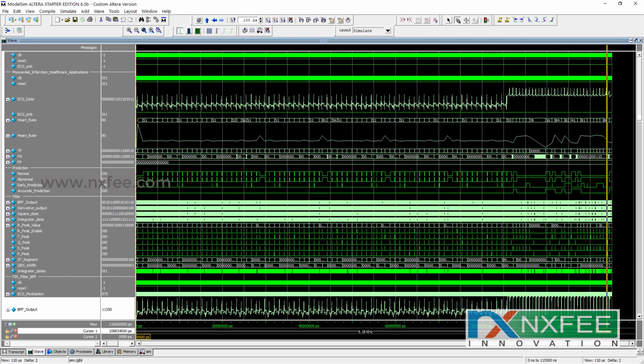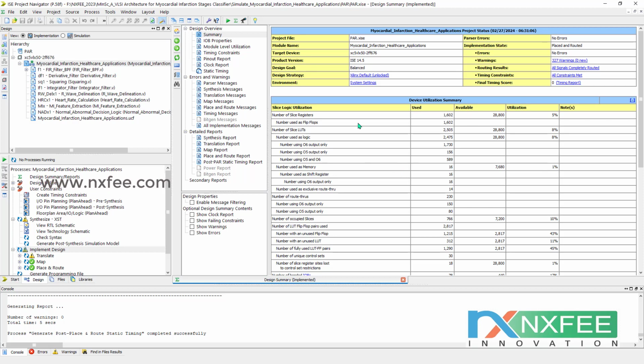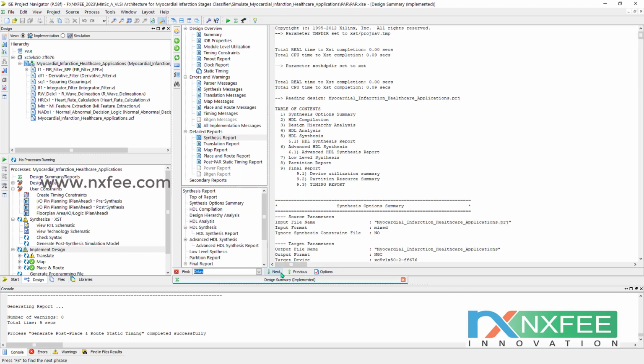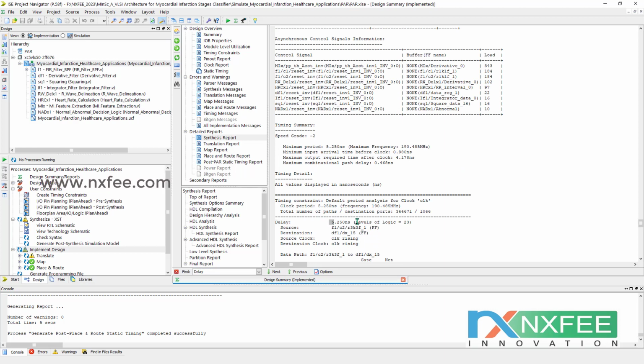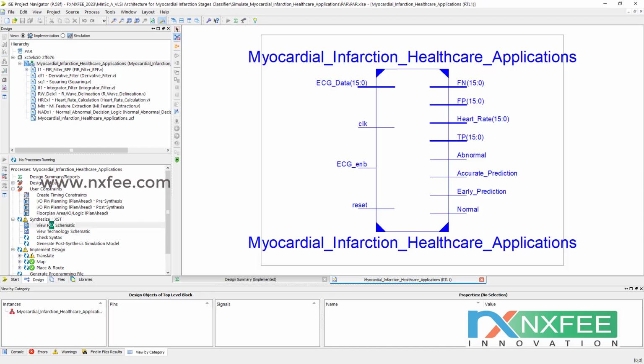That's it. This work we have synthesized on the Xilinx Virtex 5 FPGA. Here you can analyze the number of slice registers, number of LUTs, occupied slices, and IOB, and it takes very minimal utilization. It occupies only 8% compared to other works. The LUT count is only 2505. In the synthesis report you can analyze the delay, which is only a minimum of 5.250 nanoseconds.